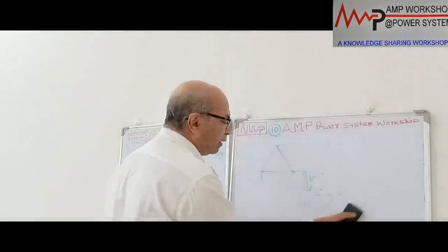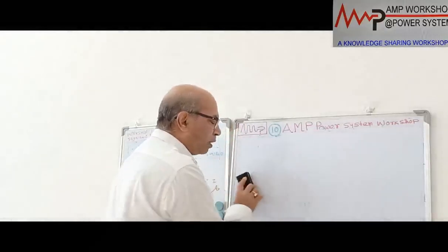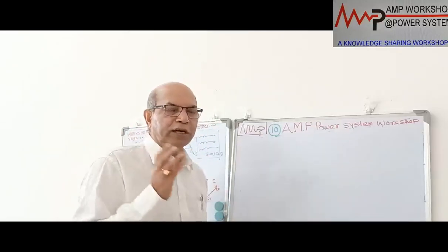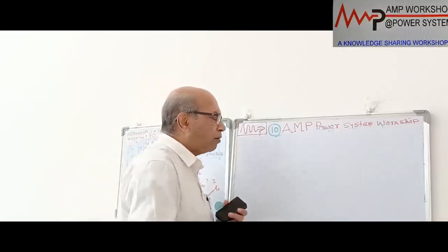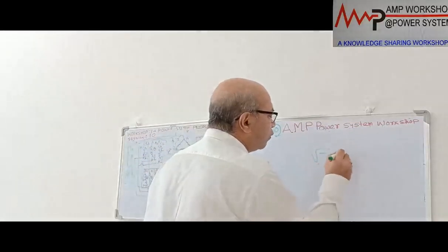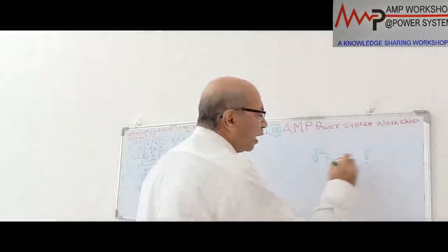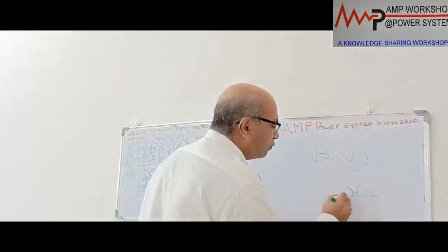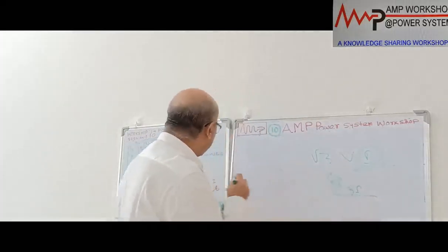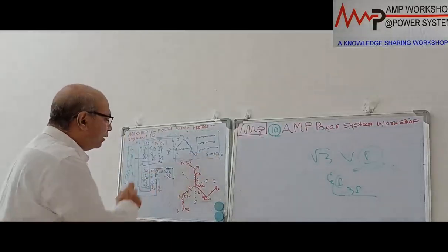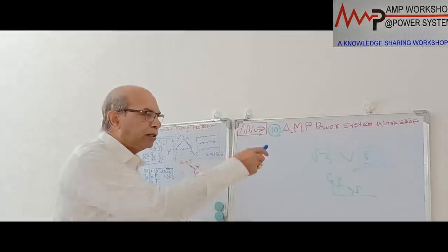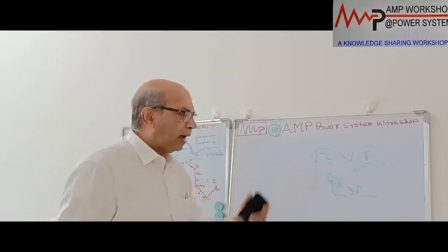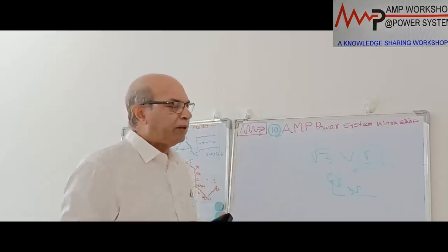This voltage we have decided; based on that, the current rating is the fault current rating, whatever fault current flows through the winding, because there is no phase current flowing in the winding, so there is no consideration of phase current. The V into I, what we wrote for the kVA capacity, root 3 into V into I, this I is the earth fault current. If the total neutral earth fault current is 3I, the phase winding will be carrying the earth fault current of only I amount, which we have distributed over here. So this is 1/3 of the earth fault current that is to be considered during the winding calculation. Okay, and 1/10 of that will be the capacity of the earthing transformer.